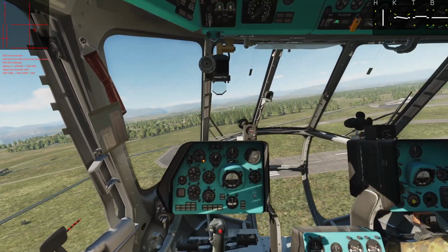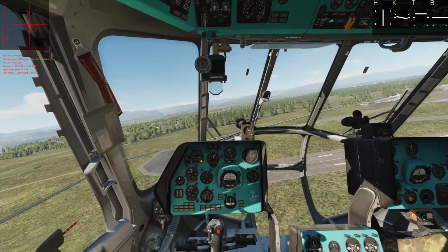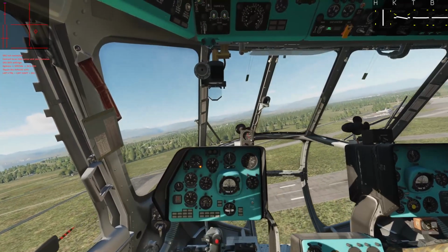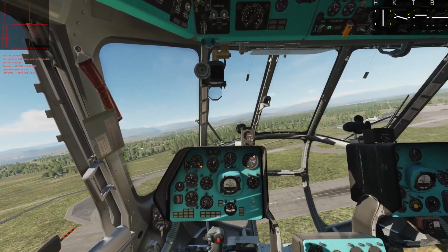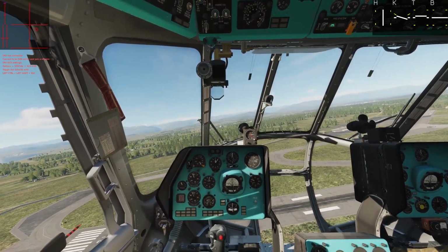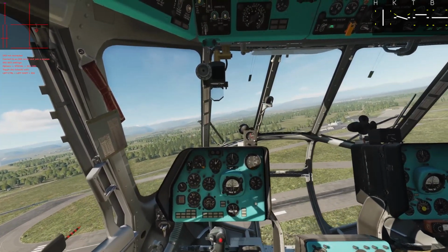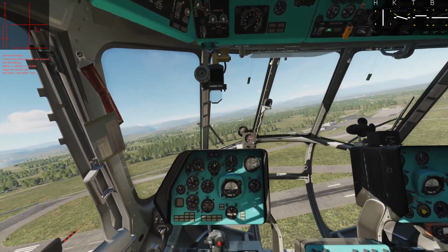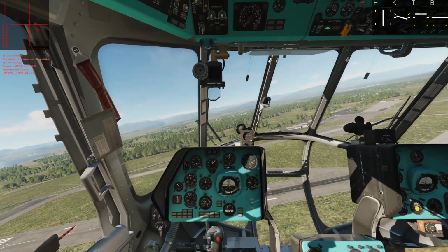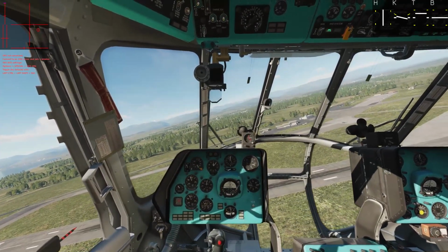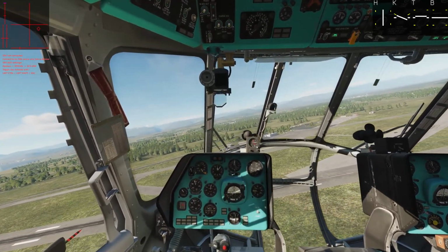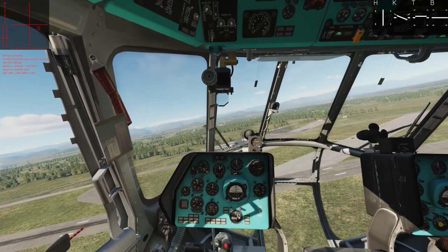And as a reminder, we are putting the tail rotor in a descent condition. Try to keep the side flight as purely right as possible. Try not to climb. And I'm having to reduce the pedal and sneak in some left pedal here. Side flight is increasing.